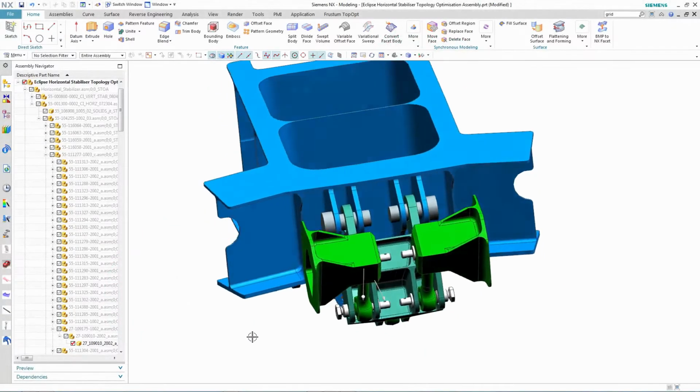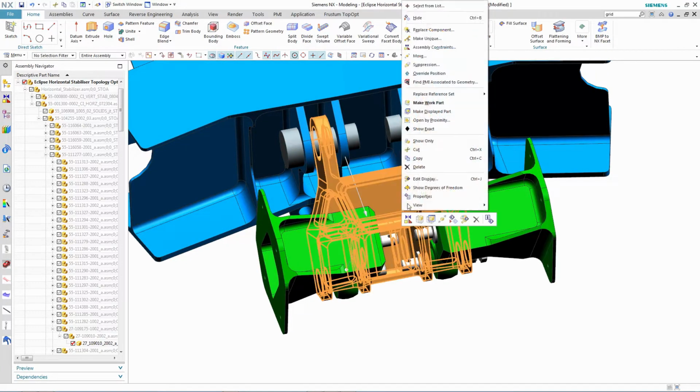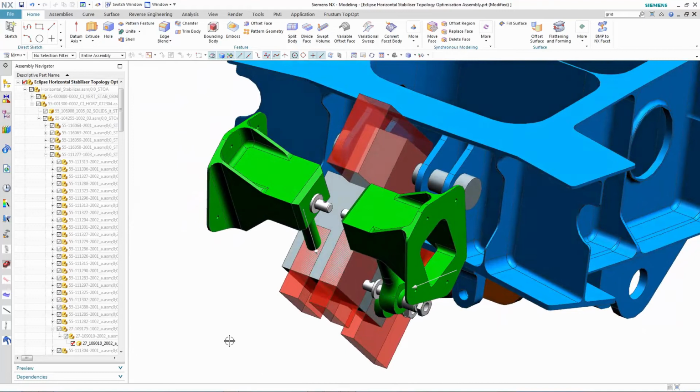But instead of using a designer's imagination for the redesign, they decide to use topology optimization to suggest a new potential design. To do this, the designer first starts with a model of the design space, meaning the area that the crank could fit within. In this case, the gray area is the design space, and only half of the design space is modeled since it's a symmetric part. The red area represents an area where we don't want the material to be placed for